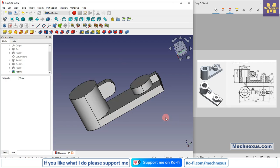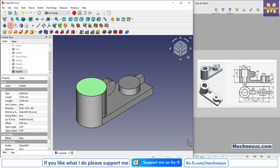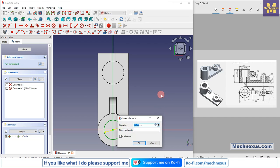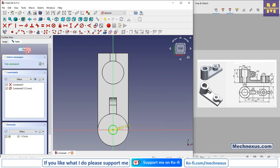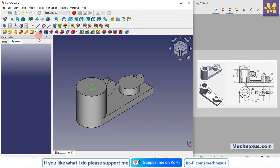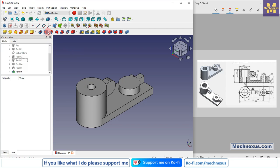Now press 0 for isometric, and we will create here the counterbore hole. So first we will create a through hole of diameter 12. Select the face and click on the sketch, create a circle, go to the diameter, and this is of diameter 12, close, and I will create the pocket, and I will make it through all. So this can be made with a hole feature as well here.